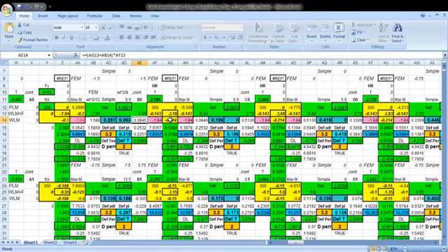Now go on to this joint. Let's say, calculate this joint. We say rotation contribution factor. So this value we calculated. Now we reach this value at column. That one was for beam, and similarly this was for beam, this was for column. Now this is for beam and this is for column.